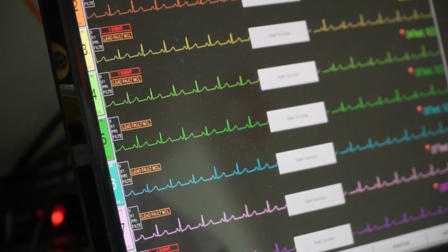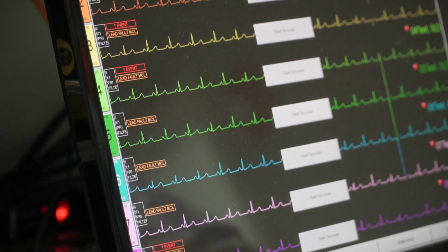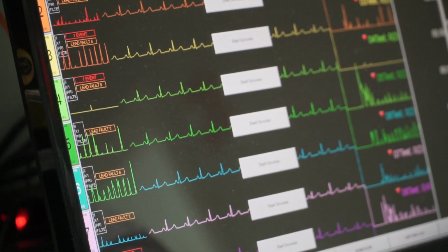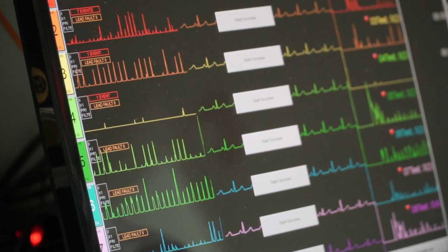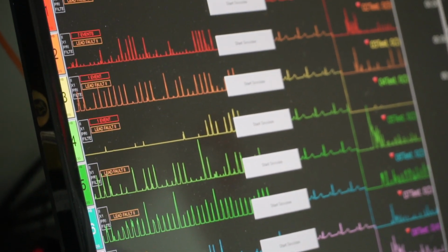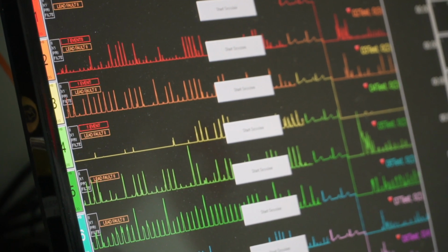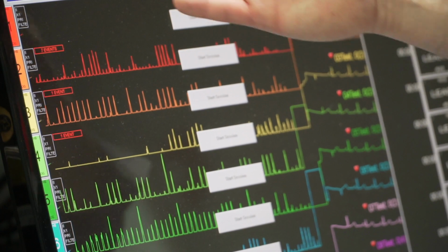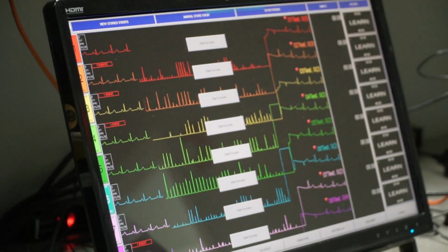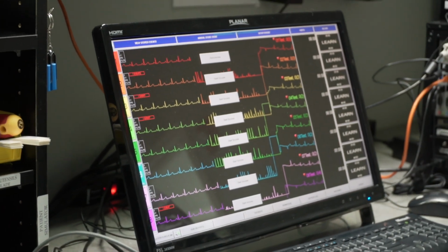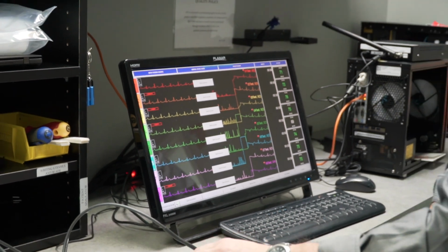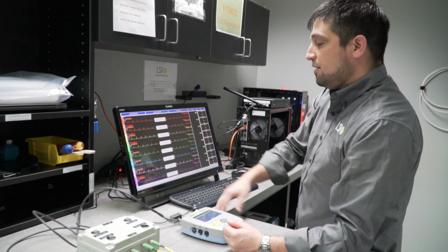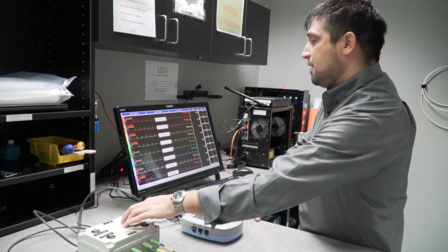We also should be able to, if we disconnect the white lead, the lead 2, and you'll notice our signal just totally evaporates or goes kind of nutty, but we also have a lead fault 2 now. And once we correct these, we'll see a normal heart rhythm come back, and the leads are good. There's no errors. We could do the same for the brown. We notice the MCL fault, and then we disconnect the red lead